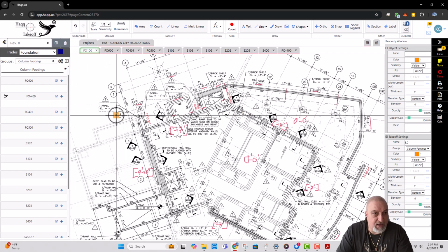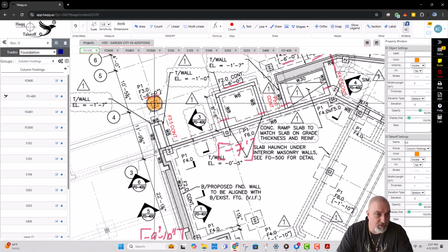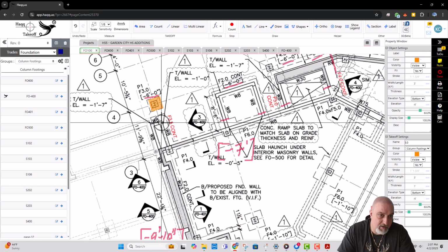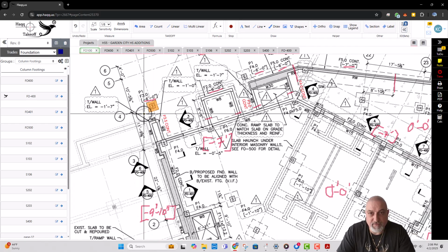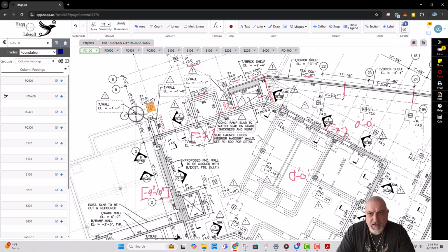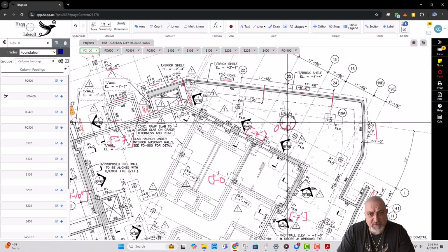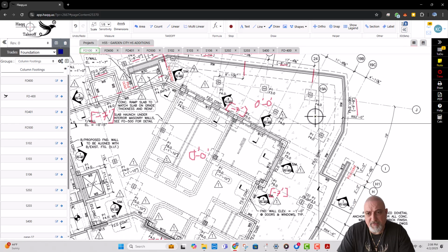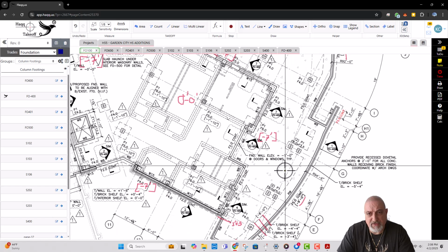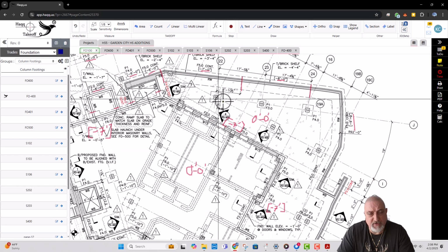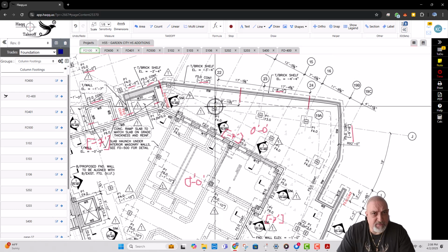But because all the F3 footings will be at the same elevation as per this F3, okay, let's add it here. To rotate it, press spacebar, rotate it, and place it. That's simple. Is there any other F3s? Yes, there are other F3s, and these F3s don't have footing elevations. They didn't put footing elevations for this. Okay, but it's simple.